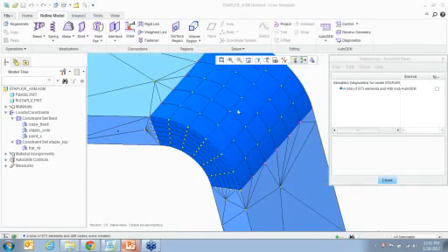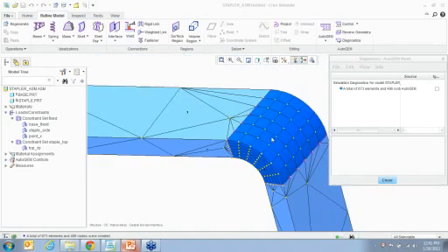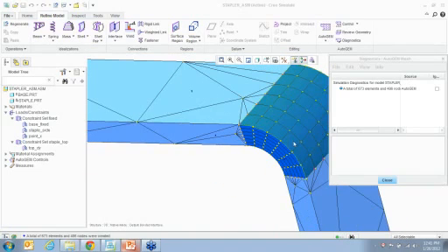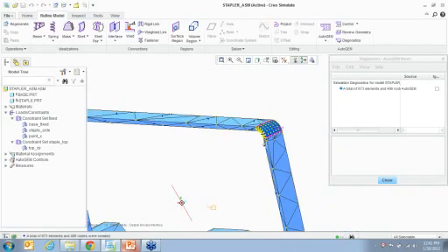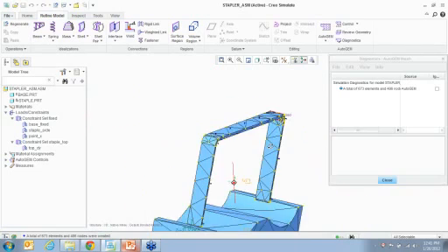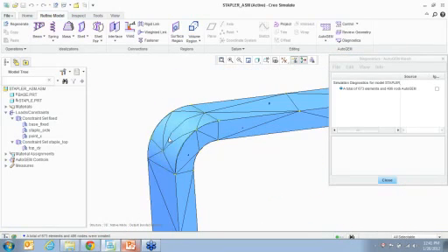I want you to see right here. That's more of a map mesh because this whole staple thing is going to bend over there. So this angle is almost going to be flat. So you want to have a more clear representation because there's going to be a bunch of stress concentrations. It's much more accurate if you have brick elements. So I'm going to create brick over there. And you notice on this side, when I don't create those brick elements, I don't get much clearer localized results.